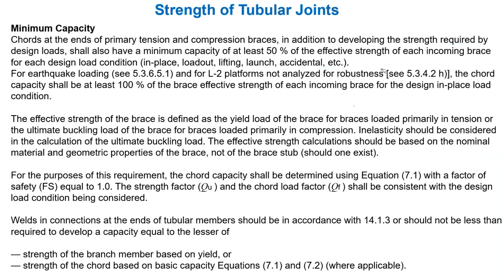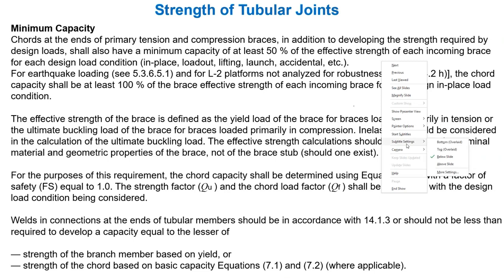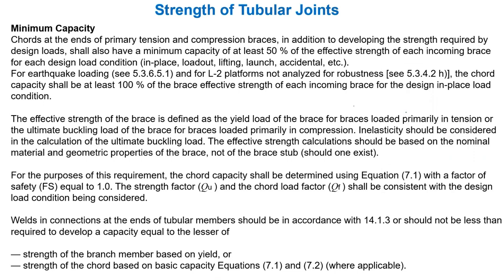I got it. No, we can't say that. Cost is one hand, safety is another. There are so many uncertainties here, and when we design this joint, I don't want the joint to fail before the member. Here, safety we cannot compromise with respect to economy. If we compromise safety for economy, then we have to bear more cost later. So safety is much more important than economy. So we need to consider this 50% strength requirement.